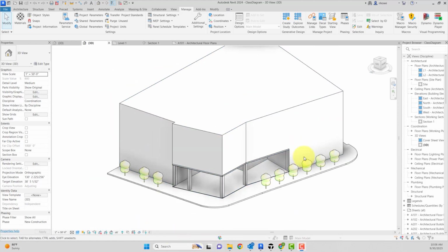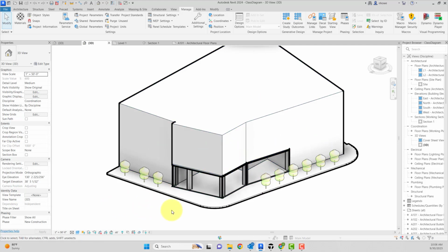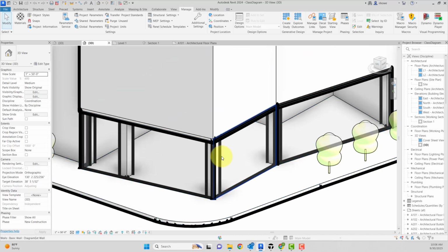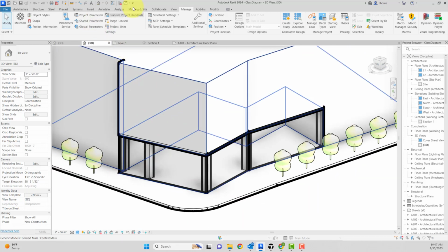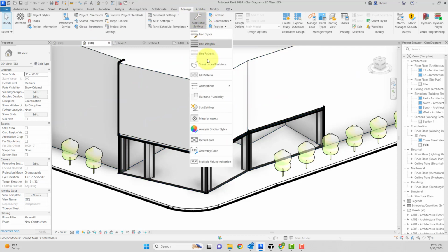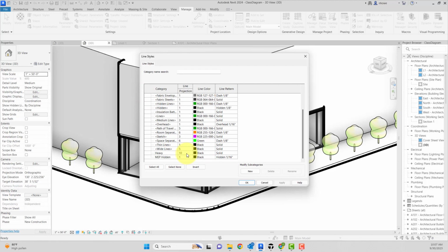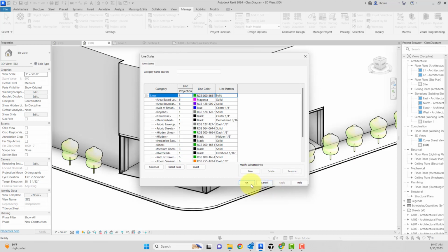So if you're like me, it didn't show up. So I realized I have thin lines on. So I just need to type in TL and suddenly this thing pops. Not sure what I'm going to do about that. I mean, I think obviously I may not want it to be so thick. So I'm going to change that to 7.